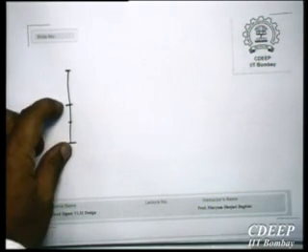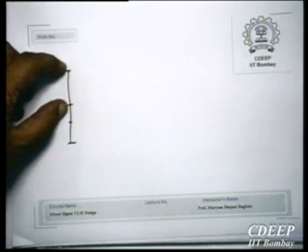Okay, now if I do it in parallel and keep on doing it for larger and larger number of bits, I will end up with a flash converter, right? Because I wanted to answer this question and then answer this question. Then for each level, if I want to do it in parallel, I'll end up with a flash converter, because this question of whether it is higher or lower than this value is answered by a comparator. So the question is, can I reuse my resources? Can I in fact say that this comparison for the upper range and this comparison for the lower range can be done by the same hardware?